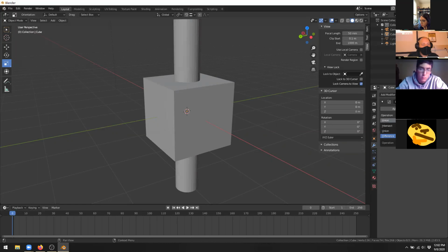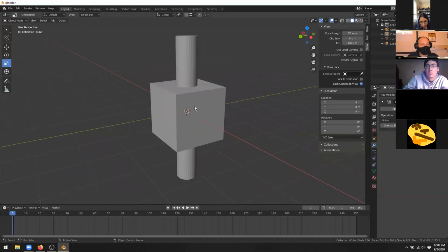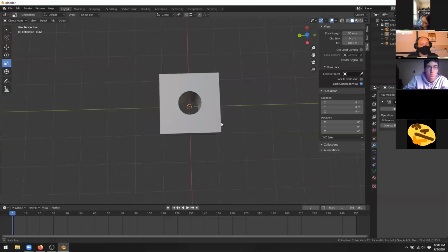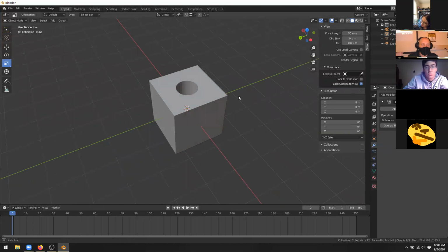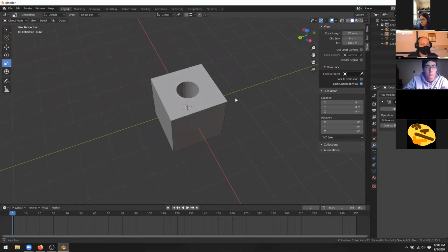You could do that in different ways as well. We can set it up to intersect. If you set the Boolean operation to intersect, you'll only see the object where the two come together, of course. Union fuses them together as one object, bless you. And then difference in this case is what we started with, which knocks that hole out of things. So again, it's pretty interesting in how it works.